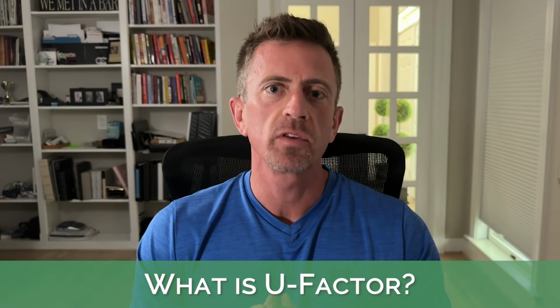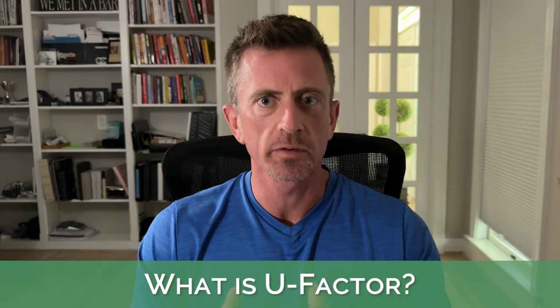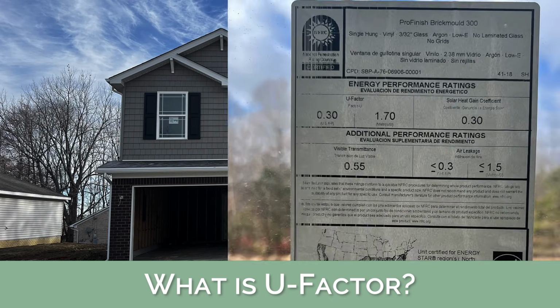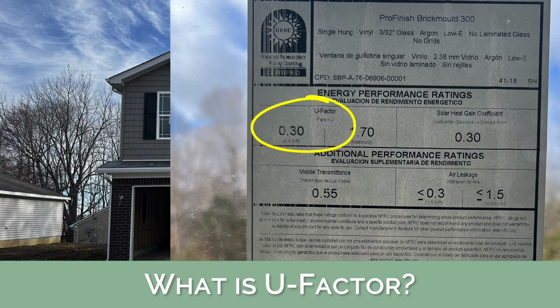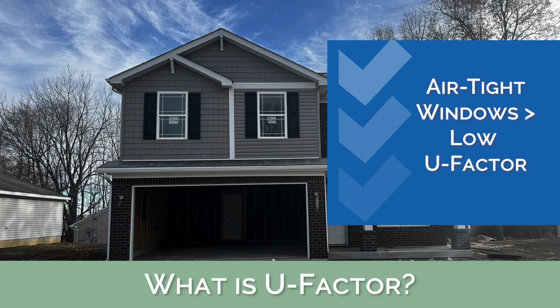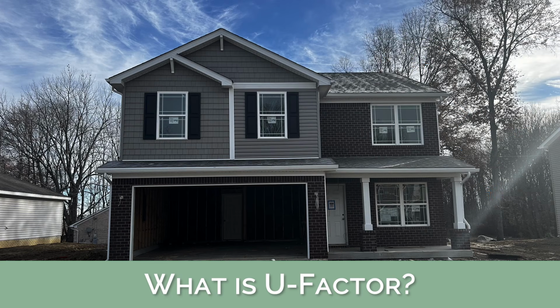If you have a relatively modern house built in the last 40 years with double pane vinyl framed windows, the U factor is likely between 0.30 and 0.45. All that said, it's more important that windows be airtight than have a really low U factor, because there's no point in having efficient windows or doors if they still leak air.